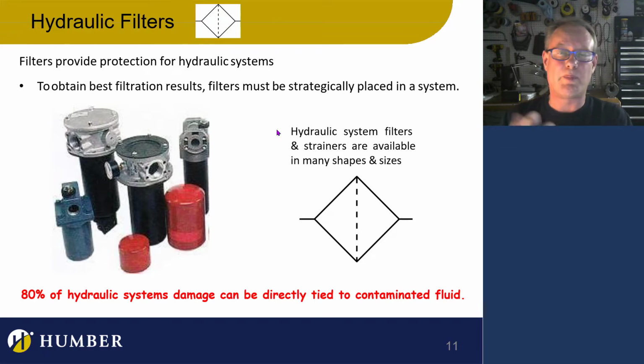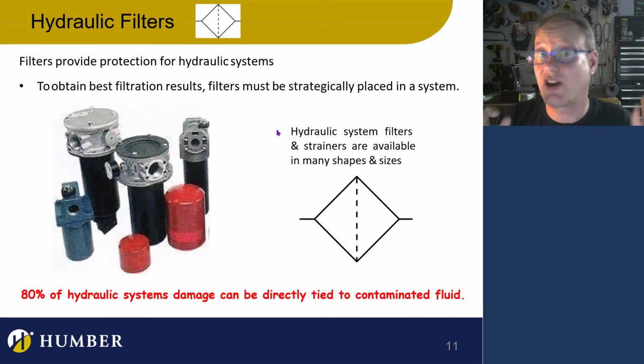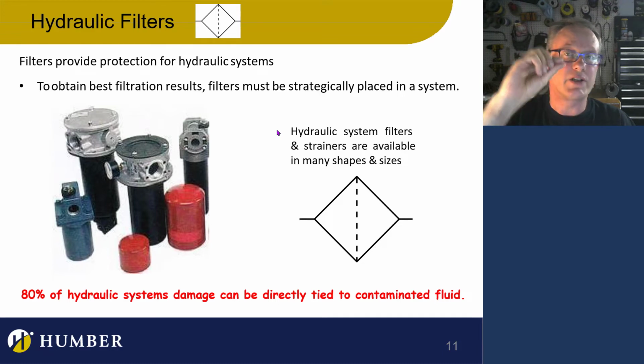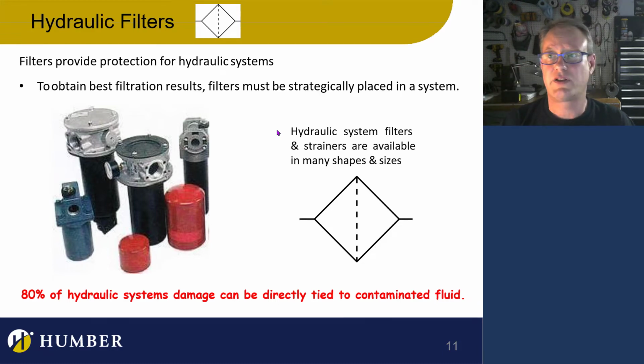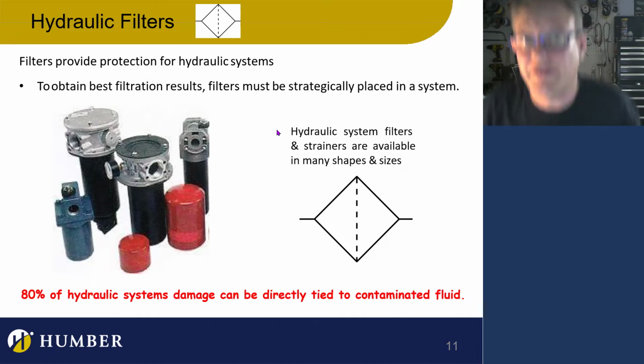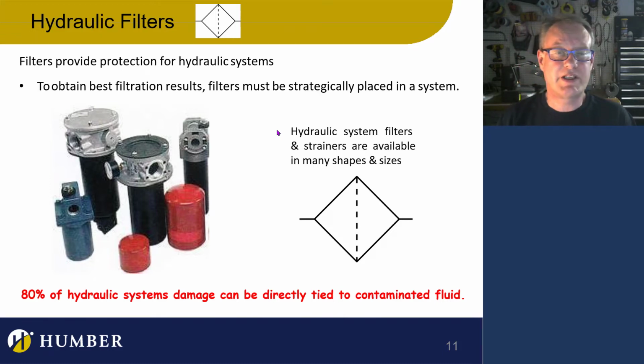Now, the actual bearings were designed to handle a certain amount of contaminants, or more specifically, the bearings were designed for a cleanliness factor. I've got several slides just on cleanliness factors. Actually really very important. What's going on is that because those bearings are working, the tolerances inside the bearings are just several microns, like 5 or 6 or 7 or 8 or 10 microns. I mean, tiny. And some of the particulates in the fluid can actually be quite large. And as soon as they get in there, they can do a lot of damage.